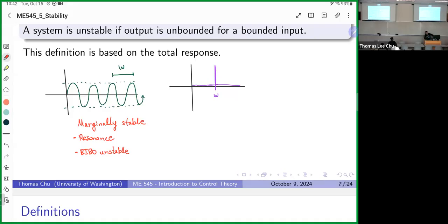Now, in the case of the Tacoma Bridge, where it's like a constant wind gust, the thing about a constant input, like a step input or impulse input, is that the input excites all frequency ranges. So it's also exciting that specific frequency as well. It's like hitting something with a hammer.